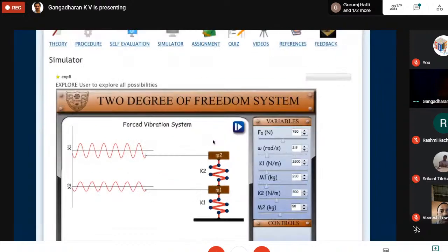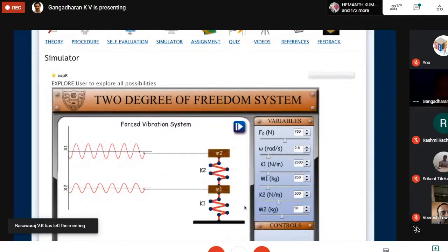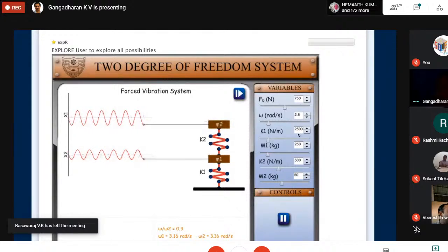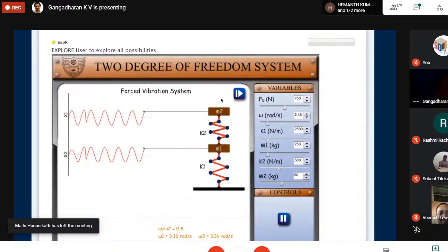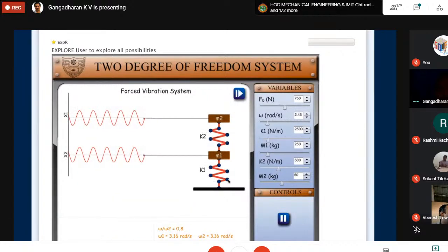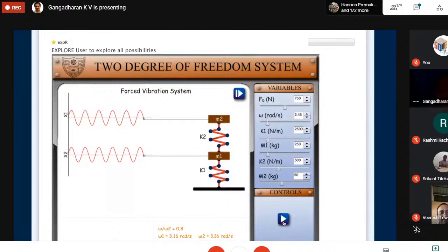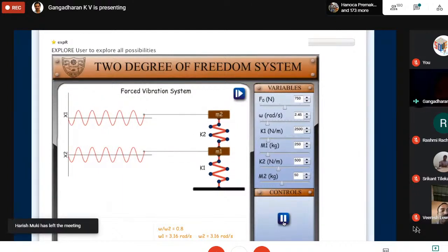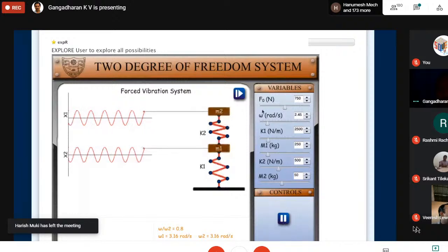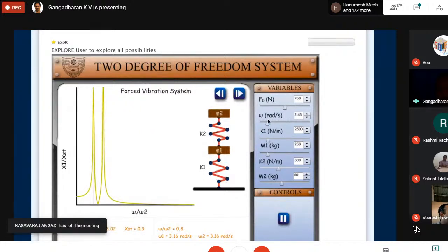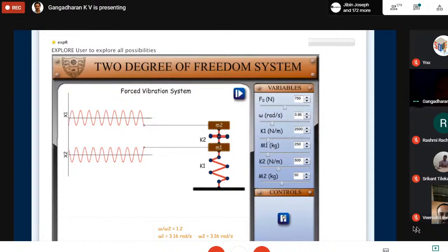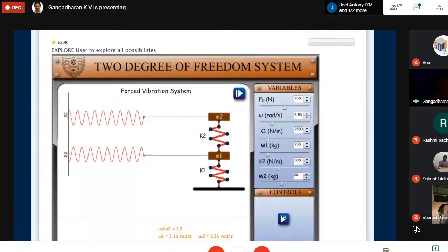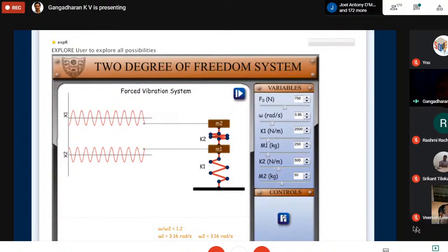Okay, so what I'm trying out is, I need this to be one parameter I'm going to change to show you how differently it behaves. Please look at this. M1 and M2 are moving together. In fact, K2 is neither getting compressed nor getting expanded. Okay, it moves up and down. Now I'm changing the parameter, the same. Okay. Now see what happens. It is moving up and down, but in the opposite direction. Okay, this is mode 2.